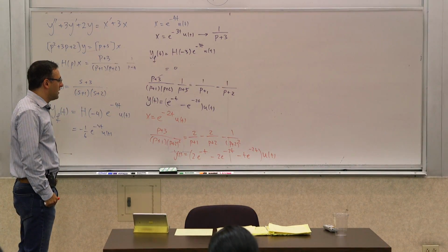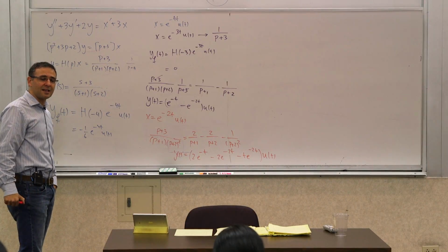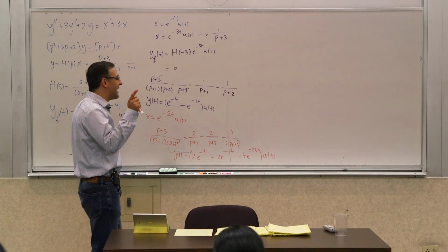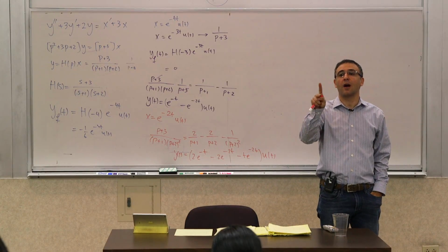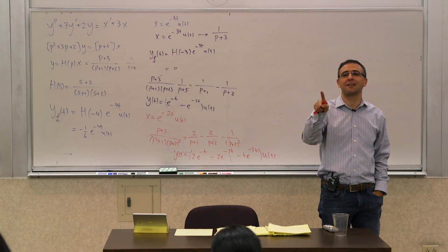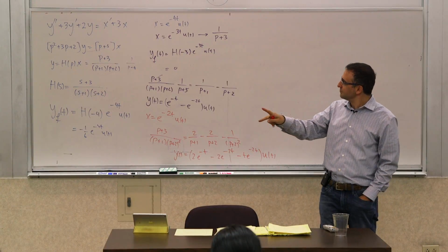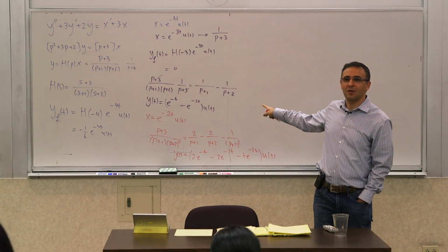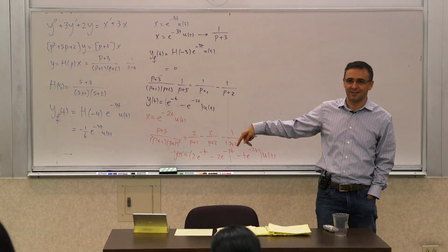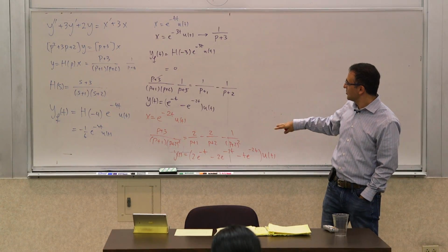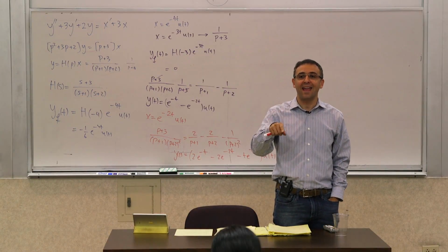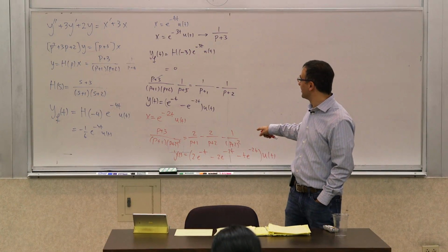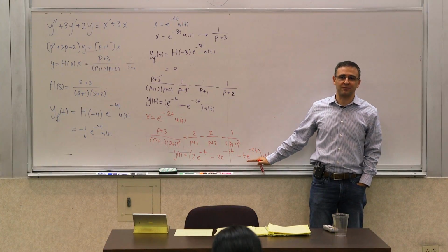Correct. Now, you earlier mentioned resonance. And resonance is related to these natural frequencies, but in a different way. That happens for a pair of complex conjugate poles, when you have, for example, an LC circuit. Not two poles of the RC type. So we'll see examples of that. So it's not unrelated, but this is more general, because we are dealing with complex frequencies.